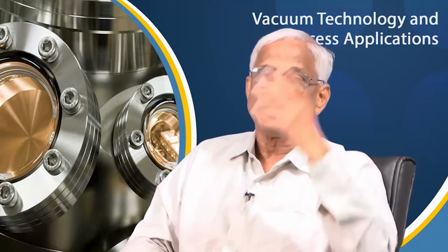You cannot do it at 10 power minus 2 or minus 3, though 99.99% is removed, because a lot of oxygen will be there, and mean free path is not very long. It is maybe 20-30 centimeters at 10 power minus 2, whereas when you are trying to deposit a film of very high quality, a 2-dimensional film, which is the starting point of electronic circuit manufacturing, etc., the deposition should be done in a controlled manner.